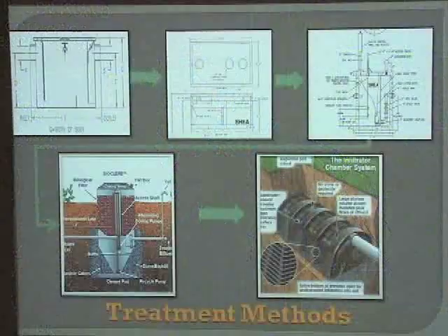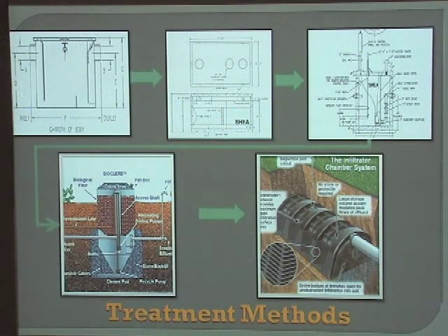Thanks, John. Hi, my name is Keith Wenders. Due to the location of the site, we weren't able to connect to a municipal wastewater treatment facility. Therefore, we were forced to treat on site. Our restaurant requires a grease trap, shown there, which just removes the grease from the prepared food and wastewater. Next, everything flows into the septic tank at the lower end of the site and then is pumped to the top of the site. This is because the lower end of the site is too close to the coast and there are poor soil quality conditions.